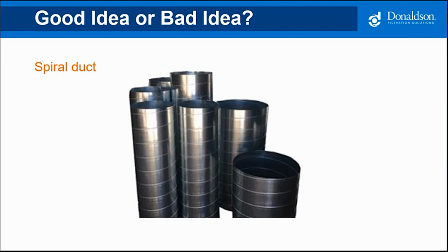Now, the disadvantage with the spiral ducting is if you have a facility and they're constantly rearranging, adding processes, moving equipment, and moving the ductwork, this stuff is dimpled and taped and caulked, and when you take it down, it can be destroyed and can't be reused, versus clamp-together style ductwork that is out there, where a cotter pin is removed, a clamp removed, and it can be inventoried, reused, expanded, etc. So, good, yes, bad, yes.